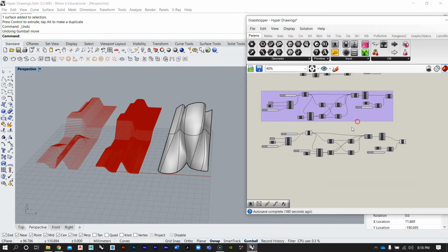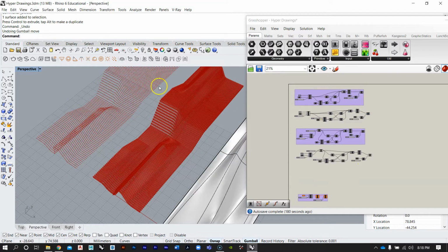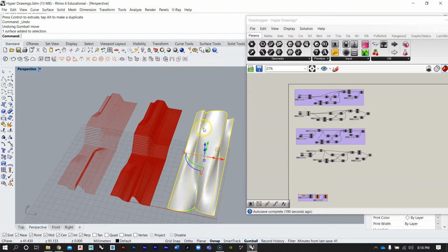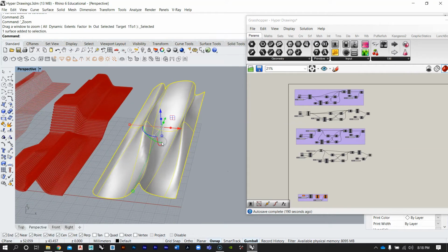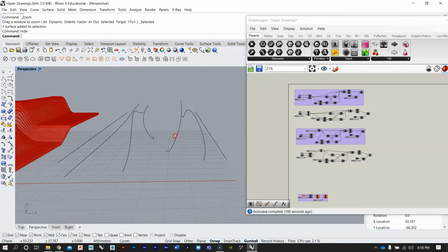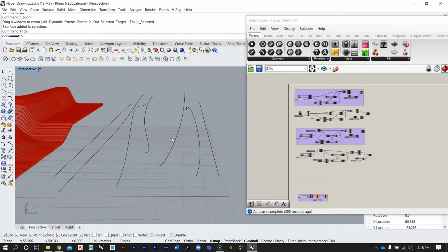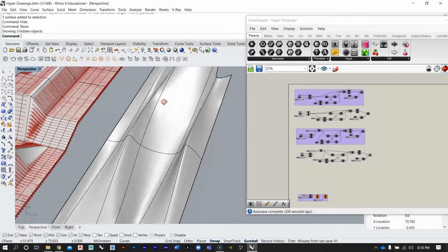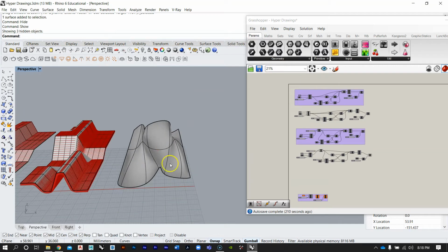Alright, so that was these first two scripts, which is just a basic contour of a complex surface. Now we're going to get into this guy. In order to create the surface, all I did was drew out some curves, and then I lofted them from right to left. And you can get some pretty interesting creasing, and you get this kind of like waviness.